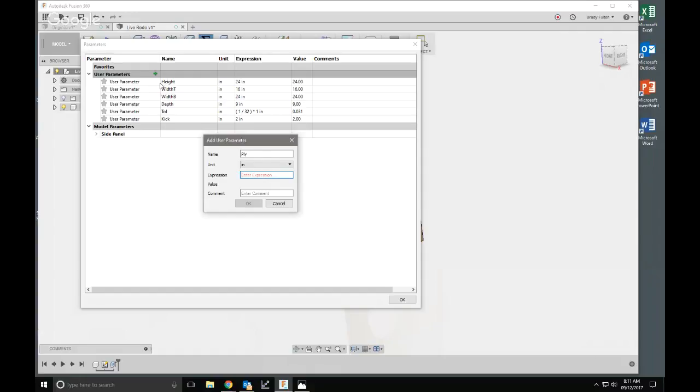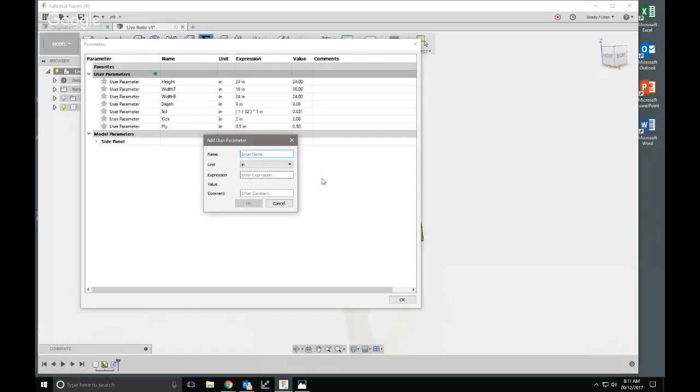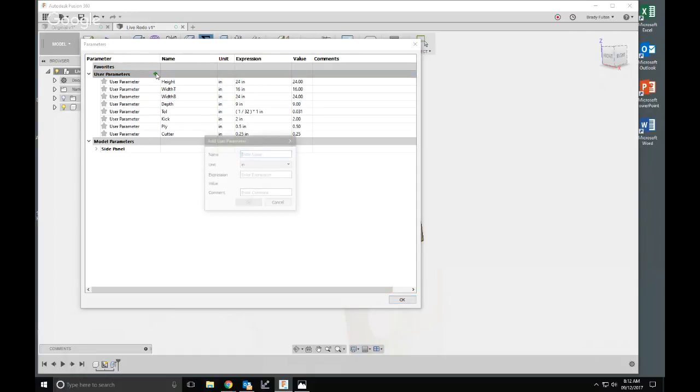So we got 0.5. I know our half-inch ply is actually 0.485 typically, but even that I measure all the time. Cutter. So this is, some people would call this bit diameter, 0.25. It's good for when you're creating things like dog holes or dog bone holes. Hook.